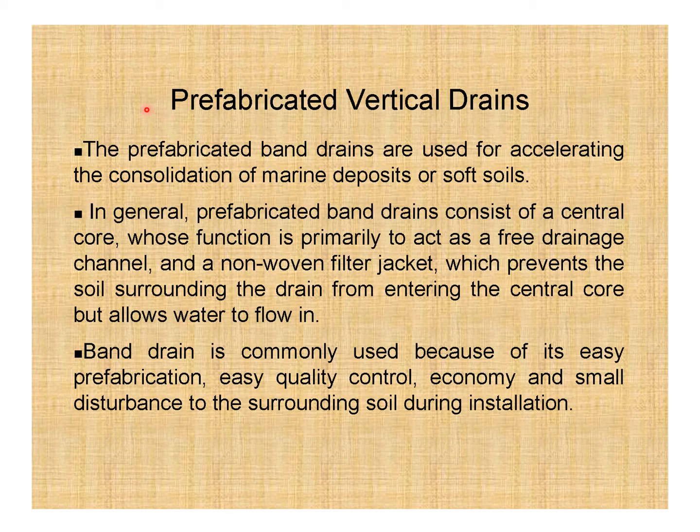Okay, now we have reached the prefabricated vertical drains. The prefabricated band drains are used for accelerating the consolidation of marine deposits or soft clays, soft soils.